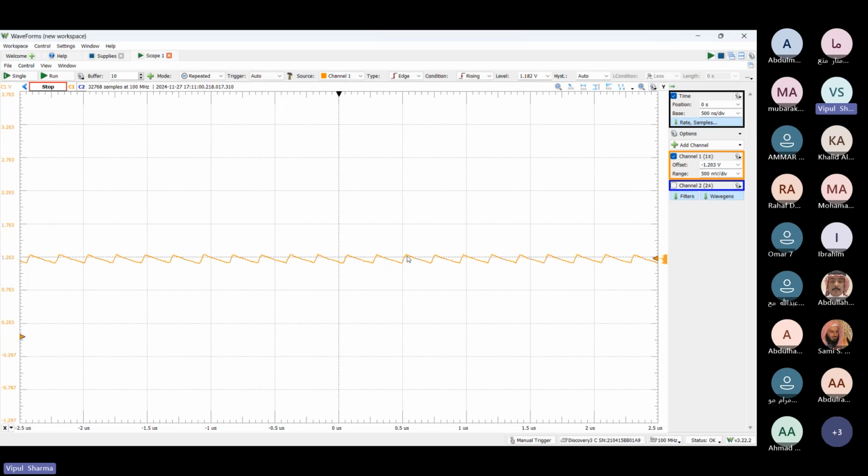The reason for this could be, I think I will try to explain it. Inside the chip I am using a digital pad to take out this signal. Although this is an analog signal, I am taking it out from the chip through a digital pad, and that digital pad is powered by a clock. The clock is interfering with this DC signal and causing these ripples to form on this DC voltage. If I had taken an analog pad, where there is no digital circuitry involved, this would have been a constant DC voltage.